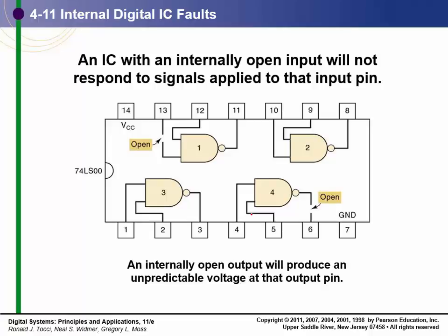A few minutes ago, I was talking about pin numbers for the 7400, which is a quad NAND gate. This shows internally how that chip is connected. And as you recall, we were using pins 1, 2, and 3, and then 4, 5, and 6. That shows one NAND gate. VCC is our pin 14, and ground is our pin 7. That's standard for all 14-pin TTL parts. That's a standard connection.